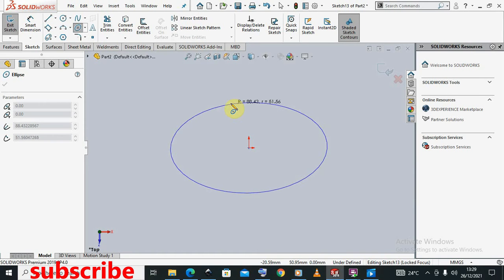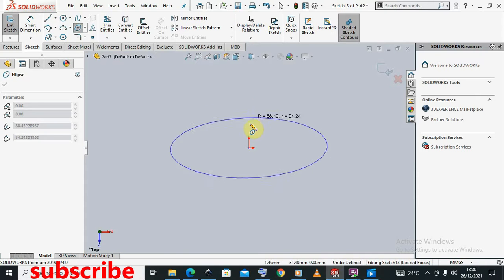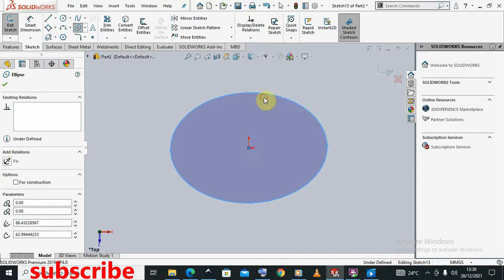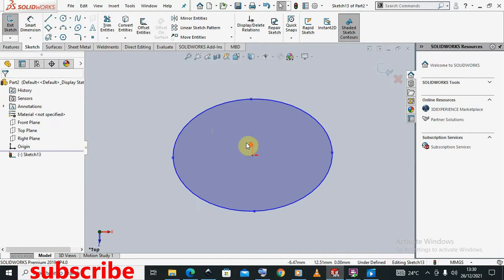As you are dragging at first, what you are getting is the major, and when you take it up like this or along the X, what you're basically doing is getting the minor, or the small r, that's 62.61. So you click somewhere and you would have completed your ellipse.